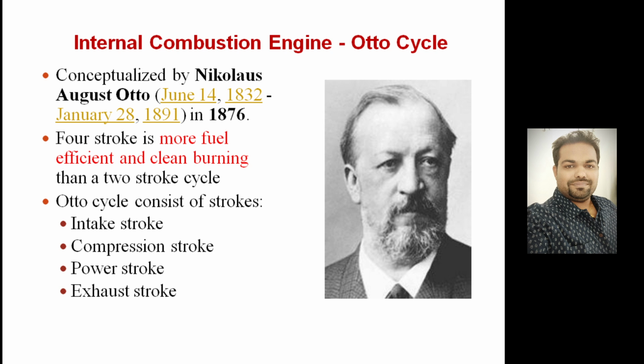Then the piston will move up and compress the air. At the point where the piston reaches top dead center, the air will get completely compressed. Then your ignition will start. You will initiate the combustion with the help of a spark plug. So all the compressed air-fuel mixture will get converted into combustible gases, and that gas will have high pressure. Because of the pressure exerted over the face of the piston, it will move down.